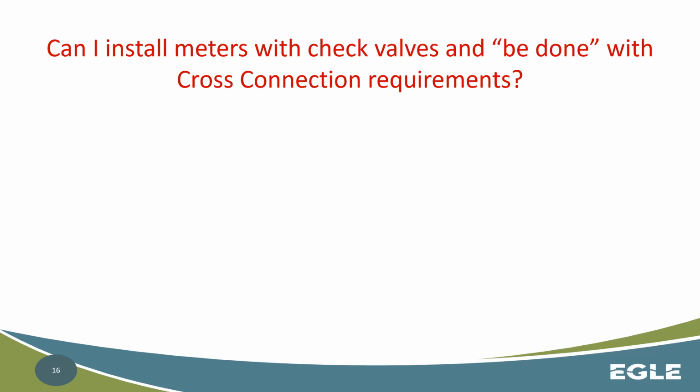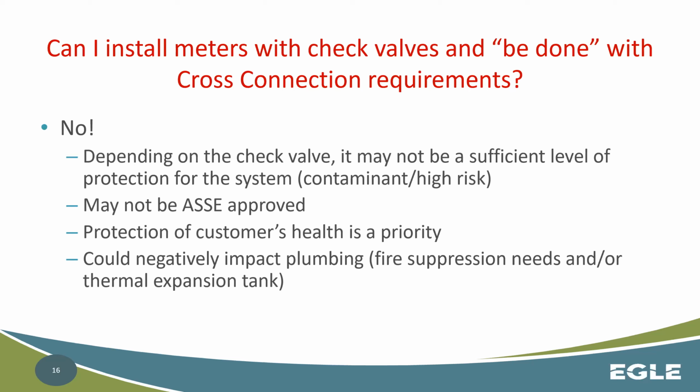Can I install meters with check valves and be done? No, you can't do that. You can't just put a check valve, because a check valve isn't a backflow preventer, and we don't know that it would be adequate to prevent a backflow if anything were to occur. Most likely it's probably not ASSE certified and it could mess up the plumbing. So no, it needs to be a backflow preventer.